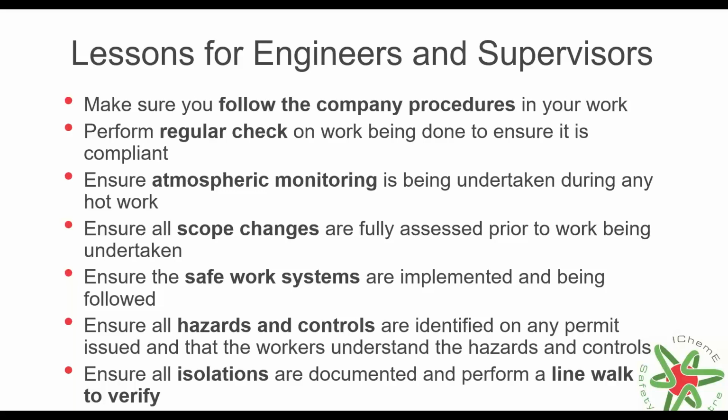Now, this is an area that we often see creates incidents from a safety perspective. And that's because the scope of the permit to work slightly creeps and people do their very best to continue to just do the job and get the work done without stopping and reassessing. Have the hazards changed because the scope has changed? Have our conditions changed? What additional controls or different controls might we need because of that scope change?